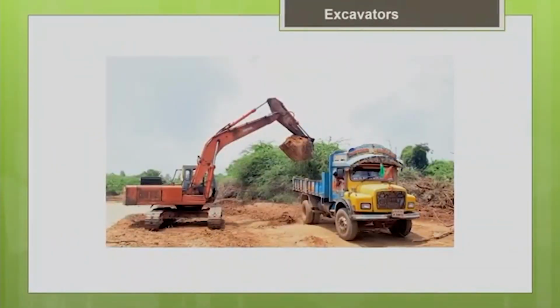As I told you, the angle of swing will be 90 degrees. Okay, the angle of swing will be the horizontal angle. The horizontal angle should be 90 degrees between the loading and the dumping position. So, the truck should come very close so that the backhoe will be able to excavate the material and load it into the truck. Okay, the common ideal condition is a 90 degree angle of swing, and also you should make sure that when the superstructure, when the backhoe rotates about the slewing ring, the tail should not hit against the truck. There should be sufficient truck spotting distance between the truck and the backhoe. That also you have to make sure.